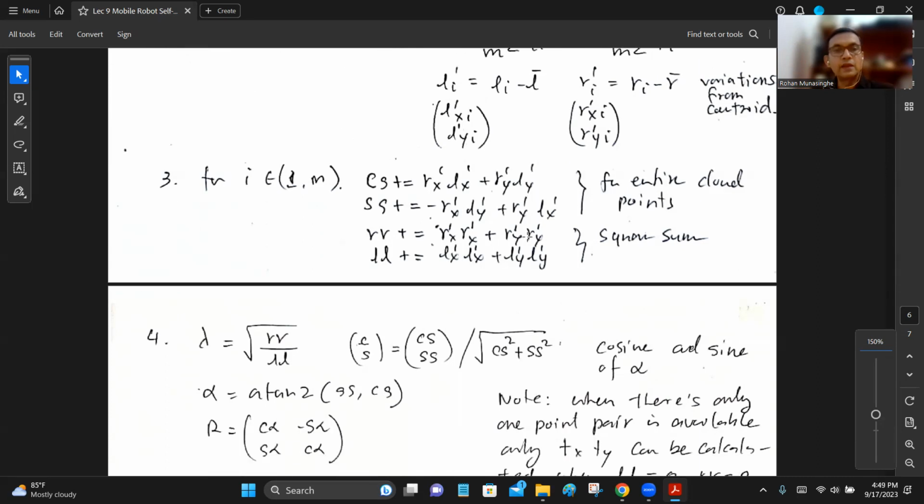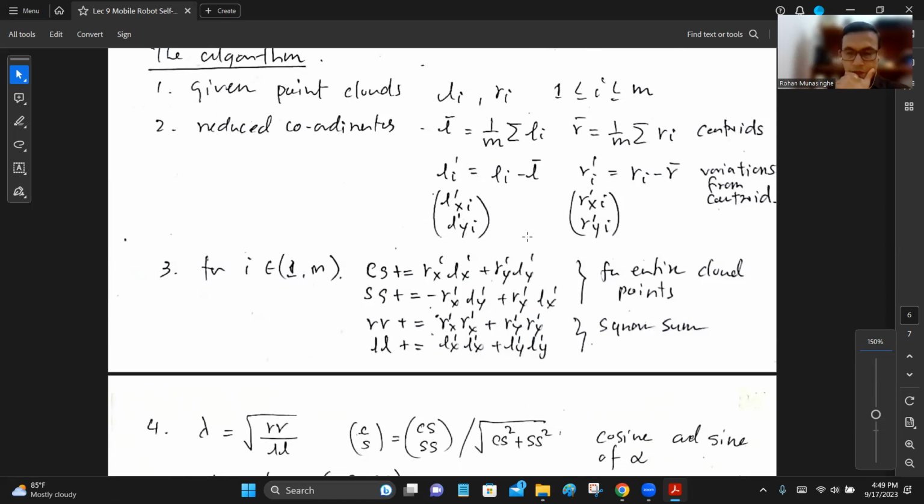Go ahead. Are all these 30, 40 landmarks given to us? Yes, exactly. For the reference landmarks, you need to know where the landmarks are. Otherwise, you cannot localize yourself. You need to have some reference. What we are trying to do is we have some observations, and we want to use the observation and the reference correspondence to shift our position this way, that way, and adjust orientation and scaling and all that, so that we refine our position more accurately, because we know our position estimate is not correct. That is the reason why our estimates are not corresponding to their references. The moment you adjust your position, the measured landmarks will fall on top of the reference landmarks.